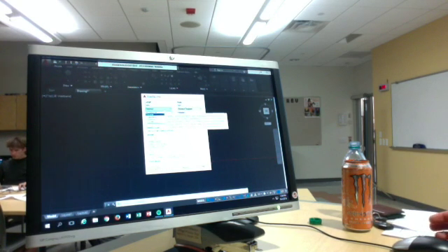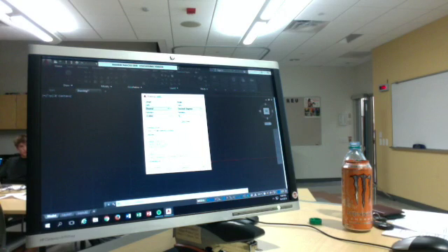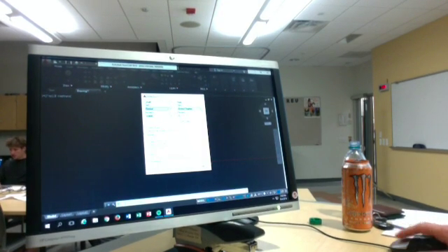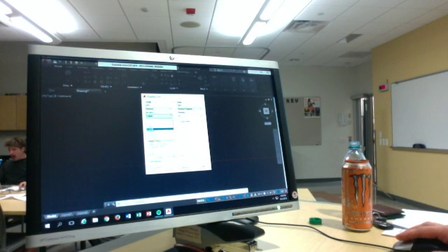It's your length dimensions. What it's asking for here is how you want it to appear on the screen. This isn't necessarily the units themselves, millimeters, centimeters, inches. This is how it's going to appear on the screen. So when you're doing, let's say, a mechanical drawing, you want it to be decimal. And then you want the precision.